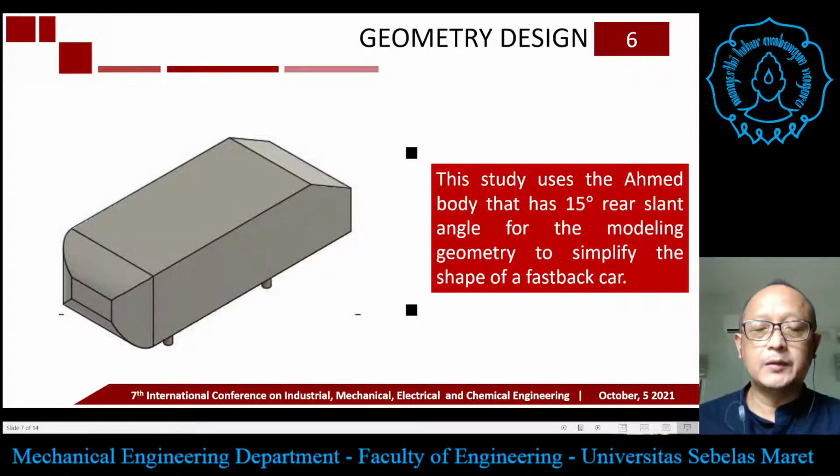To simulate our model, we simplify the fastback car into the Ahmed body. In this study, we use an Ahmed body that has a 15 degrees rear slant angle to follow the geometry of the fastback car.